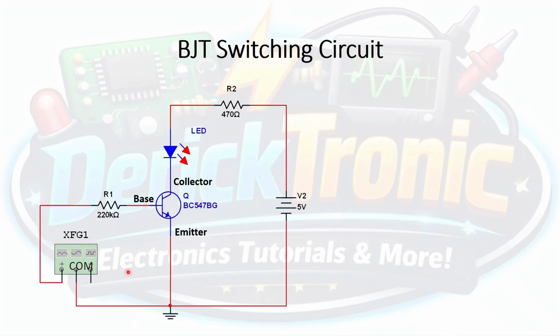As you can see from this diagram, we will be utilizing two different sources. First is the function generator here, connected to the base, and the second power source is a 5-volt DC supply connected to the collector.